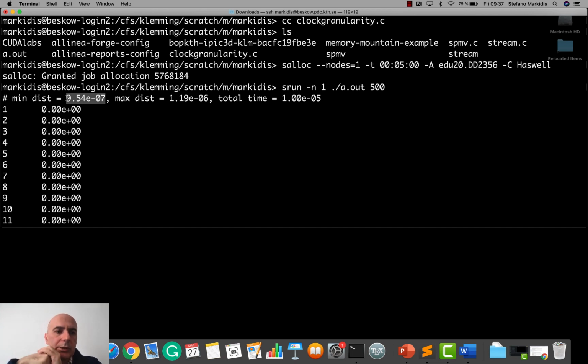It's a very precise measurement. So what we also ask you to do in the assignment is to look at a different way to develop timers. In particular, we ask you to use one of the registers of the Intel processor called RDTSC, that is the timestamp counter, TSC, and it is basically a register that is giving us a value of the elapsed time since reset time, expressed in clock cycles, right?